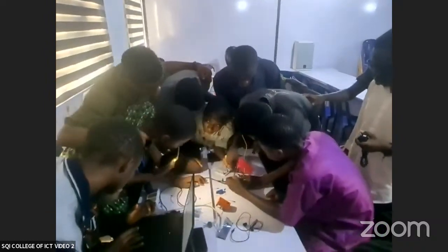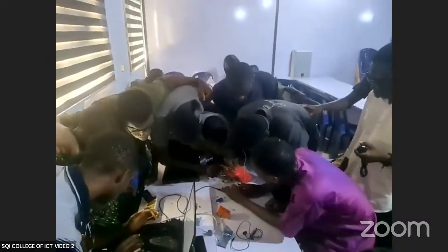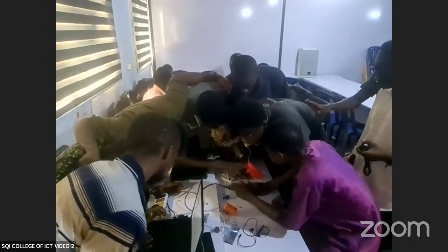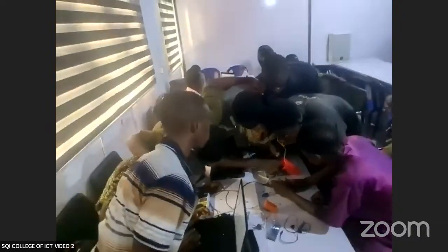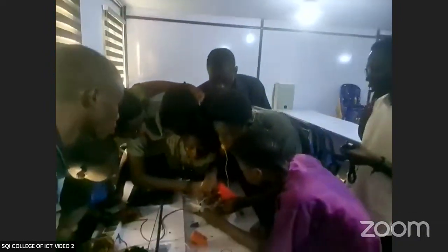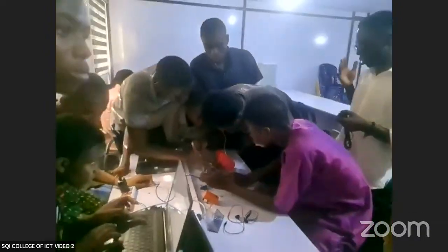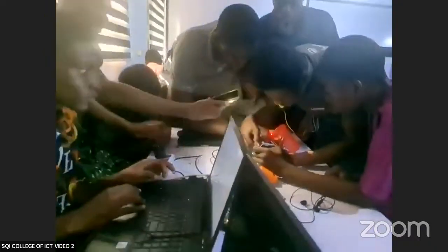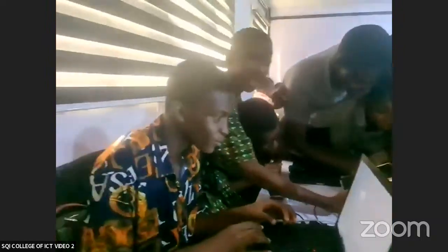All right, run it again. Remove it and remove that. 1, 0, 1, 0, 1, 0, 1. Something is not connected. That's called a floating state. Let me stop again. Something is not connected. Check the breadboard.